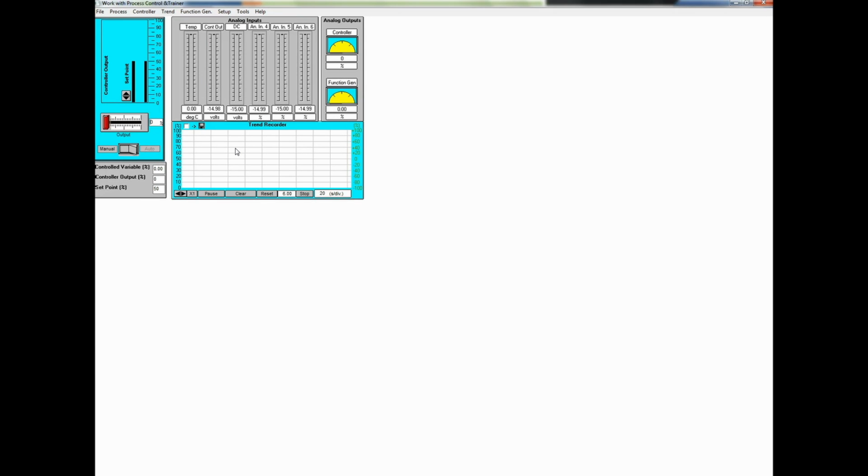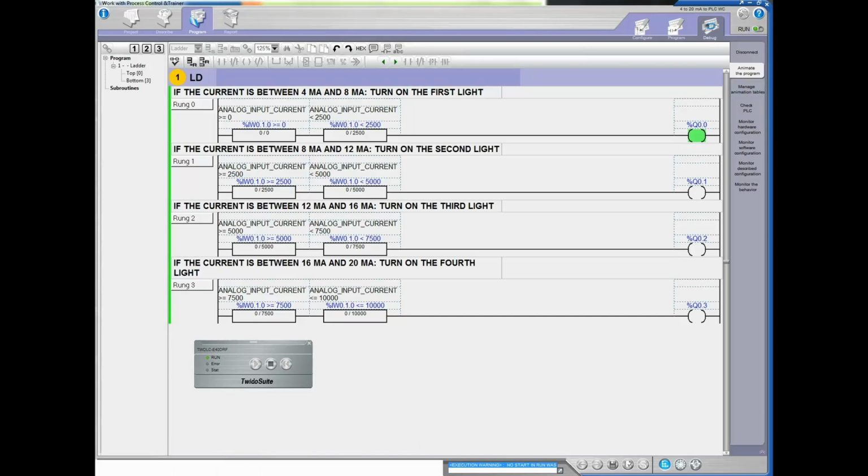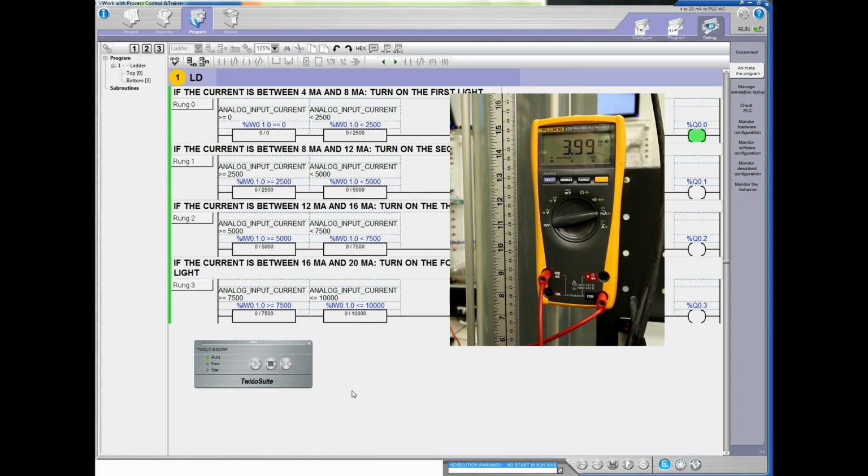And now what we're going to do is increase the voltage to our pump through this program. That's the only reason why we have this program on right now, is just to increase the voltage to the pump so we can increase the level in the tank. So we'll do that by putting this at roughly 50%. And my tank is slowly increasing in level, so I'm now going to bring up my PLC program. I'm going to close my drain valve. My fill valve is open now.